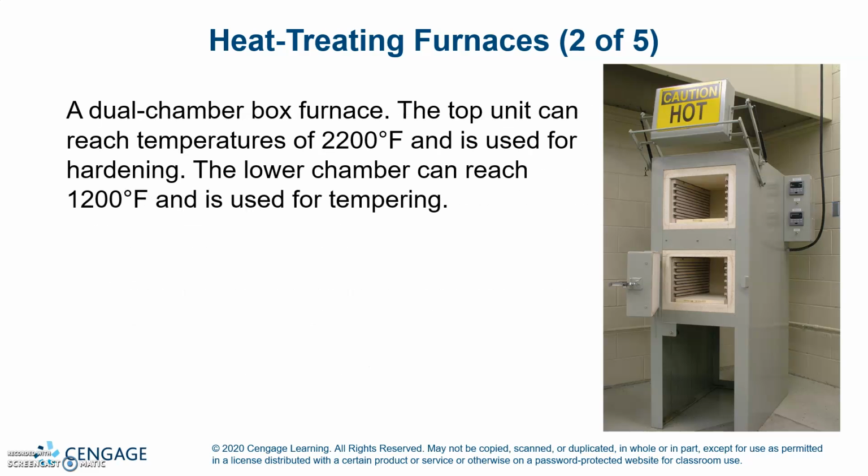A dual chamber box furnace. The top unit can reach temperatures of 2200 degrees Fahrenheit and is used for hardening. The lower chamber can reach 1200 degrees Fahrenheit and is used for tempering.